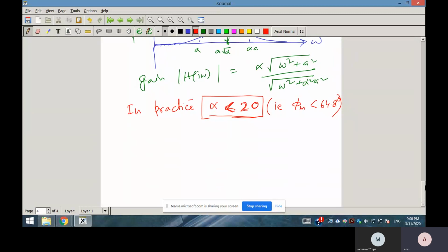In all other books, the design is a little bit iterative. So that's why I will not follow all the other books. I will follow only the N.K. Sinha book. It is an algebraic method, and that method I will follow. So the algebraic method to design a lead controller.